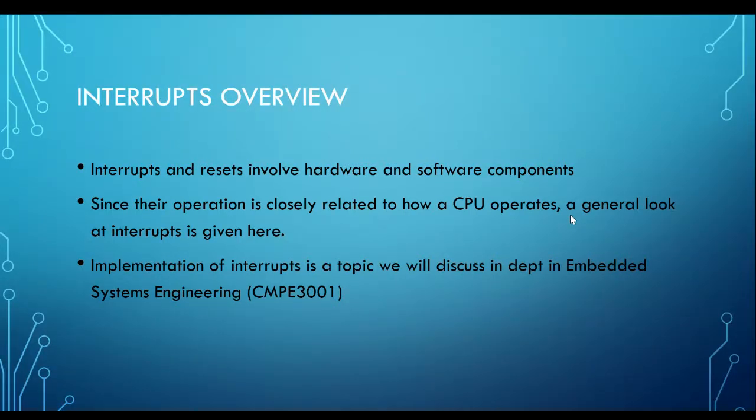This concept, interrupt and polling, is something you can implement when you're doing these projects, especially anything that deals with the user. The user input functions are unscheduled. The CPU does not know when the user will key in something. So I sincerely hope that you do something in your holiday sessions, then you'll be able to appreciate these concepts.